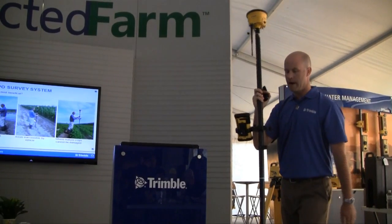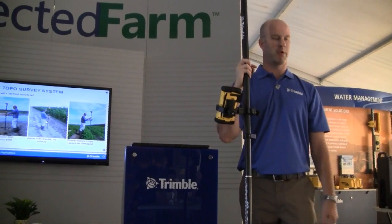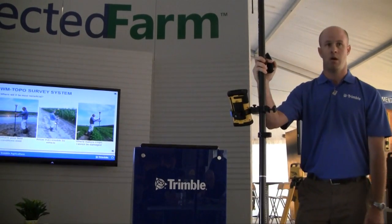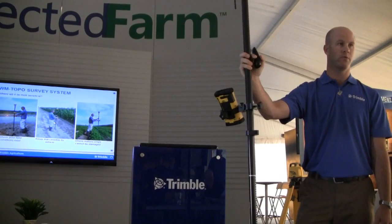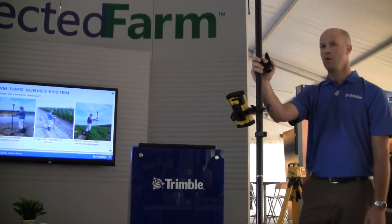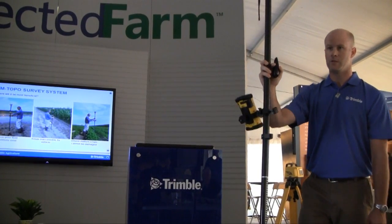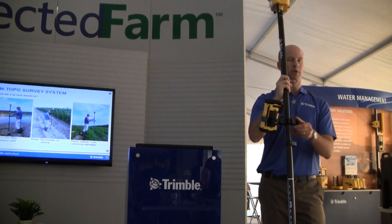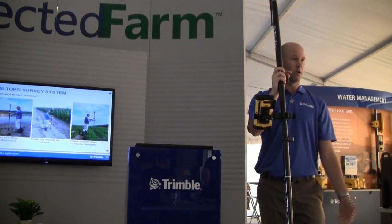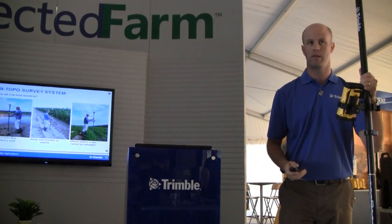The second one is areas where we cannot get out with the vehicle for topographic reasons such as ditches. We can take this system out and walk through the ditch to collect those additional points. And the third and final one is where mature crops are in the field. So we don't want to go out there and collect topographic data with a vehicle and crush crops. So what we can do is take this system out and walk through the field and collect those topo points.